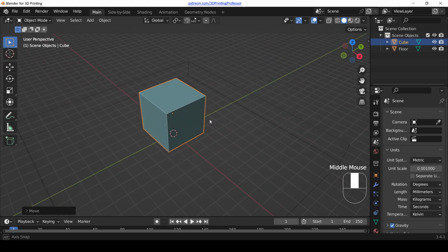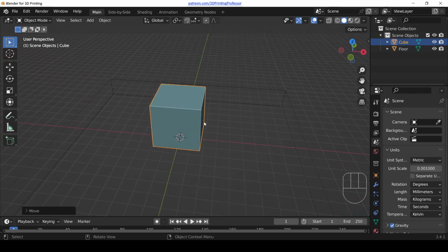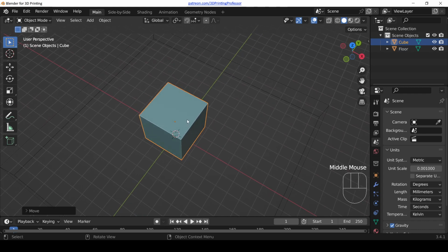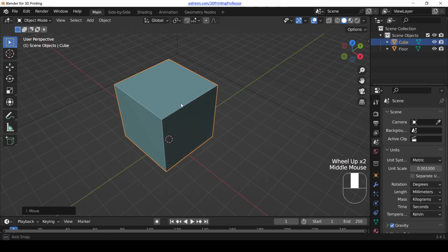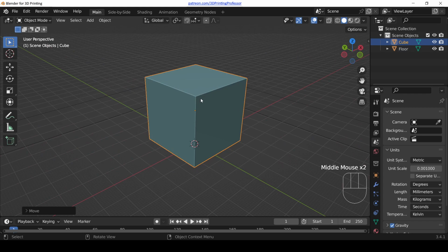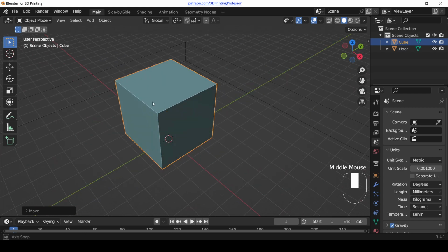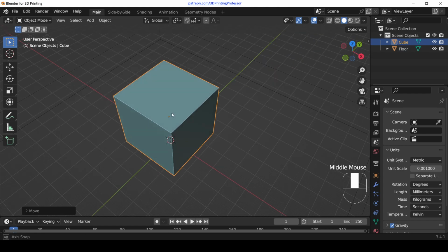Now, in Blender, individual objects aren't these parameterized things that you can go and change some parameters on to change the shape of them. They are rather just broken down into the faces, points, and vertices that make them up, but we can edit those directly, meaning that while in the past we've been able to work with the individual shapes, we can now make our own shapes. How do we do that?